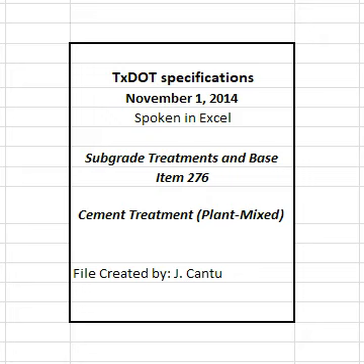5.2 Cubic yard in final position. Cement treated base will be measured by the cubic yard in its completed and accepted final position. The volume of each course will be computed in place between the original subgrade surfaces and the lines, grades, and slopes of the accepted base course as shown on the plans, and calculated by the method of average end areas.